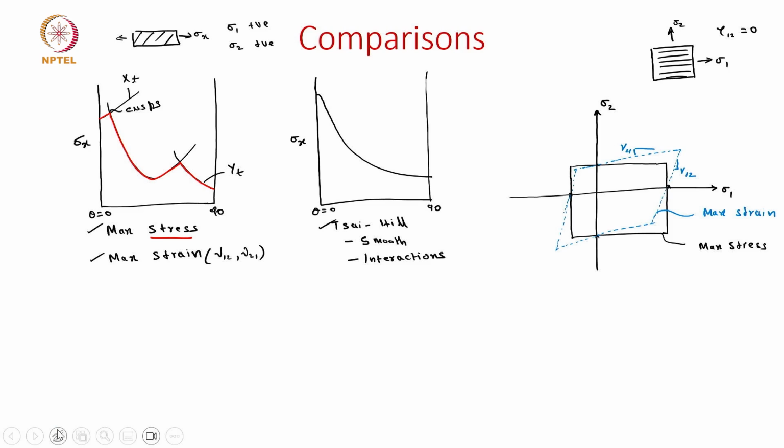So here we can also show the Tsai-Hill, but as we already know, Tsai-Hill should be drawn one quadrant at a time, because in each quadrant your choice of Xt versus Xc, or Yt versus Yc comes in. In the first quadrant we do it based on Yt and Xt. So let's say the curve is something like this, and in the third quadrant again it is another curve, and these are the curves in each quadrant.